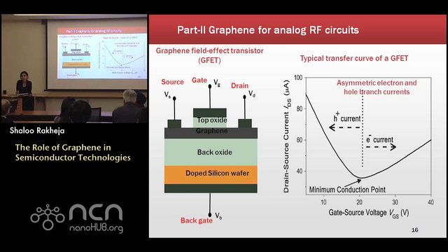So for capacitance, yes. We tried building, in SPICE, not in actual circuits, subthreshold circuits with both carbon nanotubes and graphene because they have low capacitance and they could actually beat the traditional. What is the motivation? Because the graphene nanoribbon is not a metal ribbon. It's a semiconductor. It's not a semiconductor, it's a semi-metal. The bulk is semiconductor. Yeah. You have a little bit of a band gap, yeah. So at first look, it doesn't look like a good candidate.